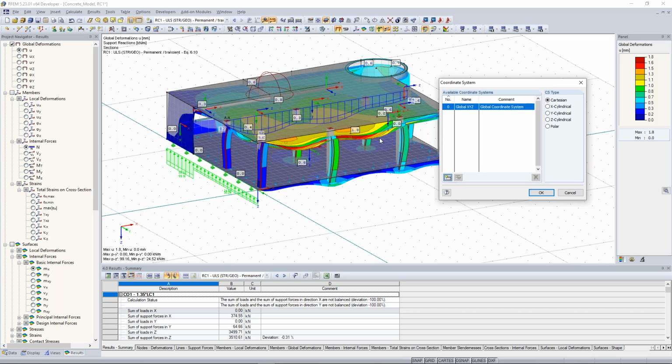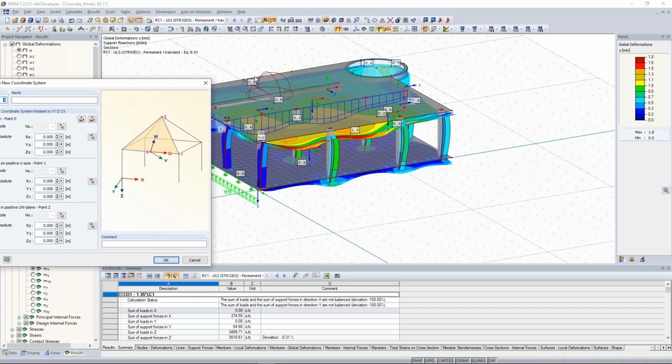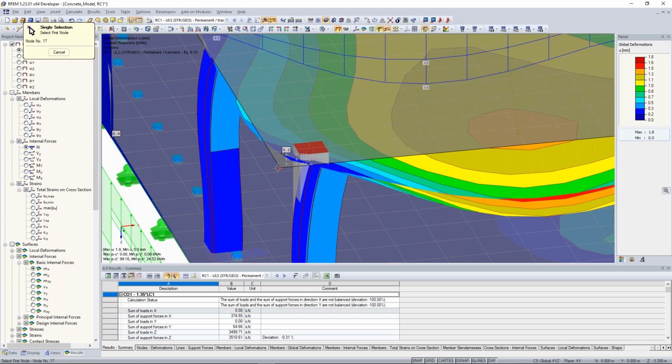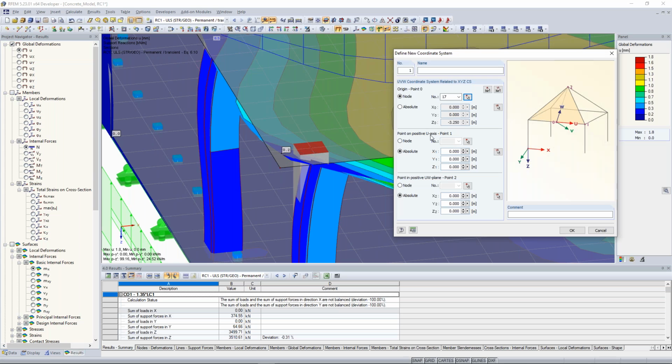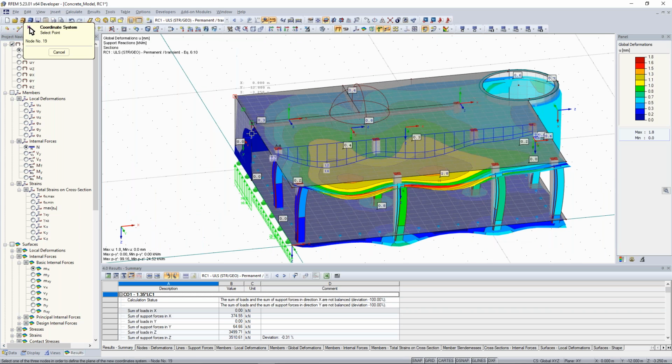And when I want to refer, maybe I say now to that level here, from another level. I can say, okay, look at these points here, U, V, W, and I can say, okay, 0. So my first node, my origin point, should be this node here. My u-axis should be, please, this node. And my other node should be, please, this one. So I created this plane here. Click on OK.